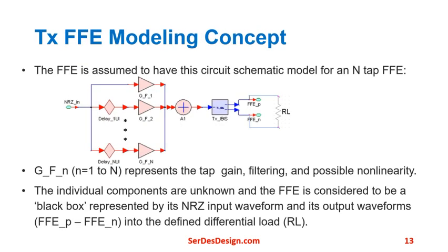Here's the transmit FFE modeling concept. The FFE is assumed to have this circuit schematic model for an N-tap FFE. Each tap has its own delay, gain, filtering, and possible nonlinearity. The individual components are unknown, and the FFE is considered to be a black box, represented by its NRZ input waveform and its output waveforms into the defined differential load.